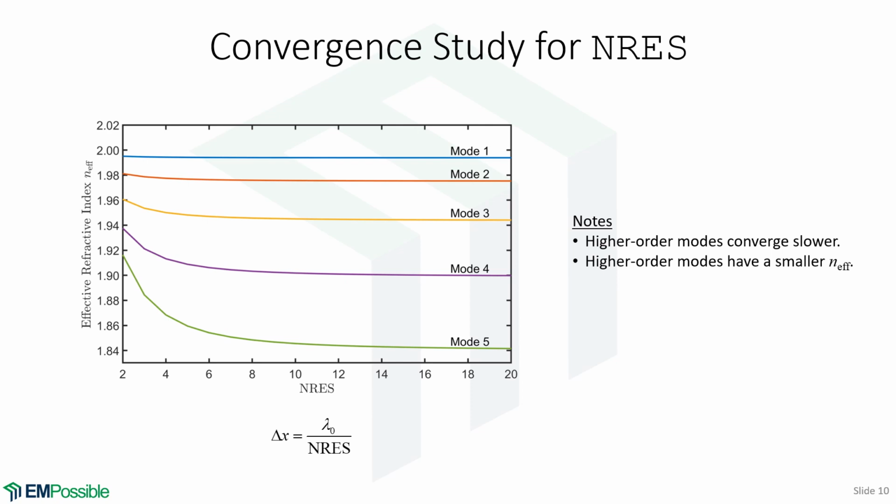So looking at this convergence study, I'm going to ask myself, where do these essentially settle into the final answer, and cranking up NRES really doesn't bias anything anymore. And I might throw out an NRES of 10 is about where things converge. Yes, I could get better answers if I cranked it up even more, but for my work, maybe an NRES of 10 would be good. If you're designing somebody's pacemaker, yeah, you might want to operate out here with an NRES of 30, but for some preliminary crude work, an NRES of 10 here is pretty good.